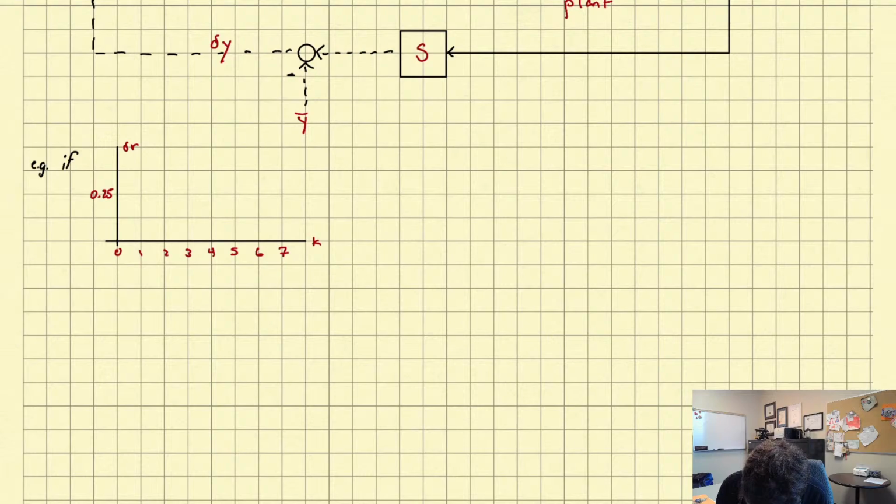Okay, suppose that it jumps up to 0.25 for a few steps, and then back to 0. What does that mean physically for our mass? It means we're commanding it to, starting from the equilibrium value of the output, 0.5, move right 1/4 of a meter for 5 discrete time steps, and then go back to 0.5, the equilibrium value, thereafter. Okay, so what are we commanding here?